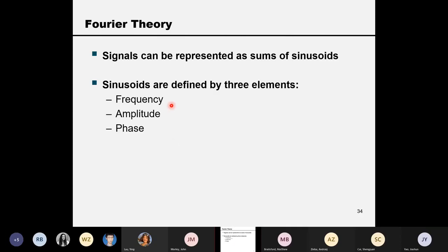Basically, the frequency spectrum is complex valued. But complex values you learned in high school, right? A complex value can be turned into the modulus, which is amplitude here, and the argument, which is phase. So that's the spectrum.